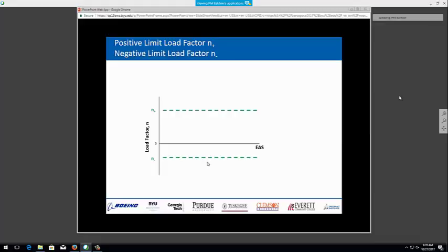So, just another picture then. This was a VN diagram from a project a few years ago. This is looking at an even smaller UAV than what you were doing, but it has all of the factors we're looking at. Turning flight here has a load factor of 3G, and we looked at a maximum Q load based on the structures.